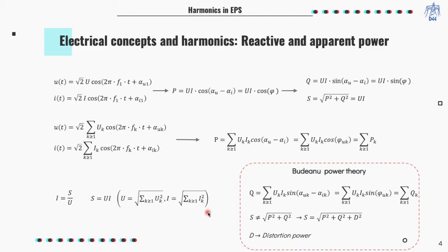On the other hand, there are several definitions for the reactive power, trying to reproduce the idea of fluctuating energy between the electrical elements in a circuit and to be useful to characterize the situation of minimum current and losses. This is not a trivial task, because in addition to fluctuating energy in a circuit, we now have the energy related to the harmonics. One of the most used definitions for reactive power comes from the Budeanu power theory, which